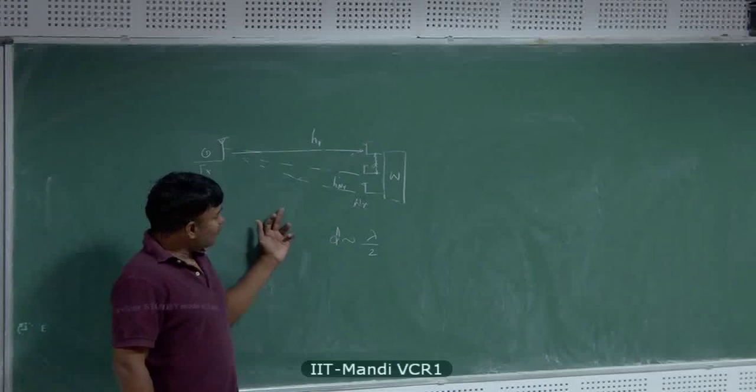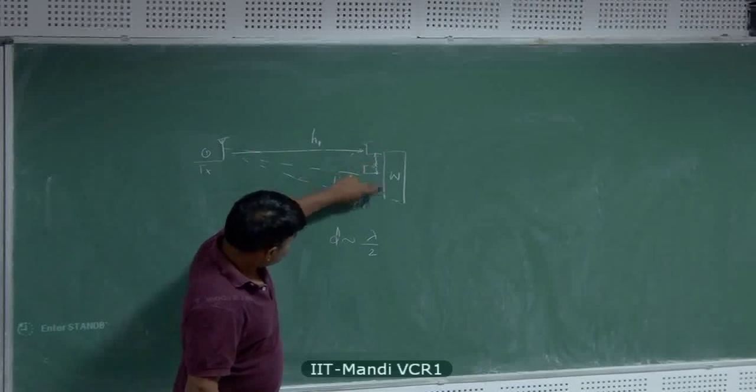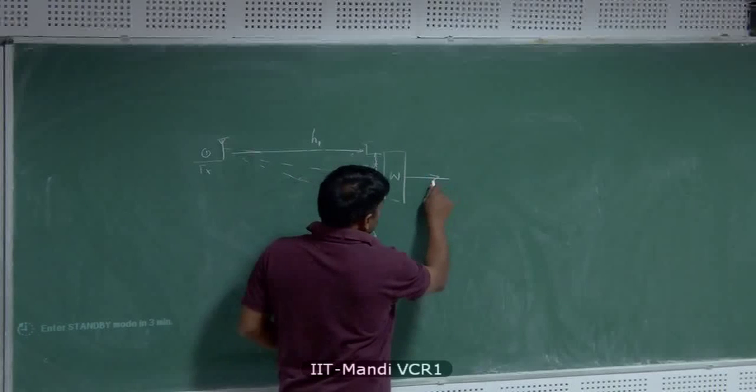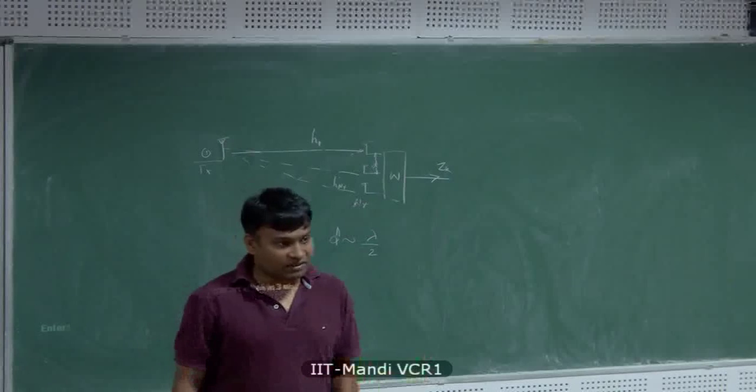What we are going to consider is a very general setup where we combine the received signals at the output of all these antennas using a filter with the complex weights W, and then it gives you a decision variable, let's say some zk, and you will demodulate your signal.